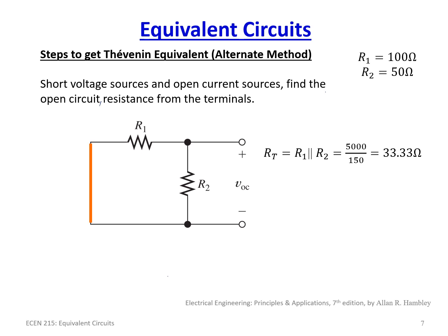So from the previous slide and this slide, the numbers agree. Using the short circuit method and solving for the short circuit current, we got 33 1/3 ohms. Using this method here, where I shorted out the power supply and then stared and computed the resistance of this equivalent circuit and got effectively the Thevenin equivalent resistance just by solving for resistance values, we got 33 1/3 ohms. So clearly the same solution.